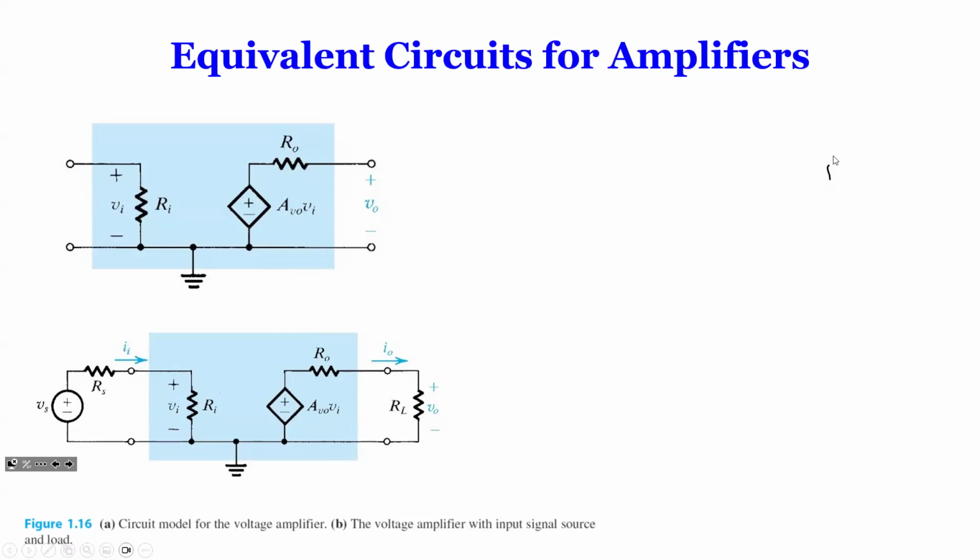For this input resistance, do you want it to be bigger or smaller by now? Bigger, yeah. The bigger the better. Because, regardless of this one, let's say this is 1K. Instead of 1 ohm, you have 1 meg. What happens? 1K versus 1 ohm, it's 1,000 times. We don't care about this one anymore. Now, of course, in the extreme case, we have an open circuit. So what is the resistance of an open circuit? Infinity, right? So whatever is applied here is applied here, regardless of how big it is, 1 ohm, 1K, or 1 meg. It doesn't matter because it's an open circuit.